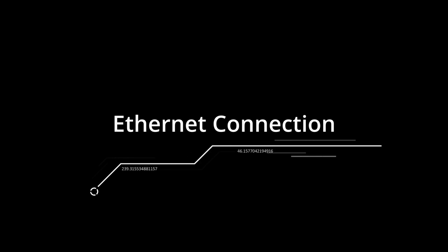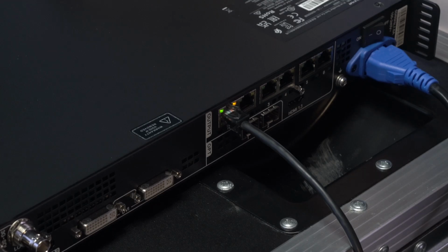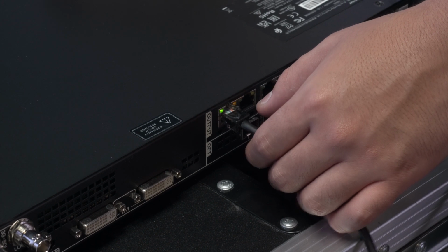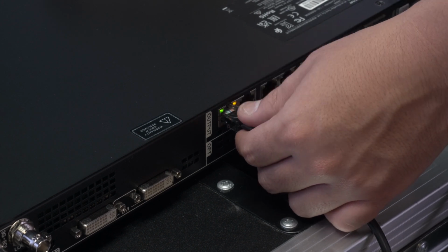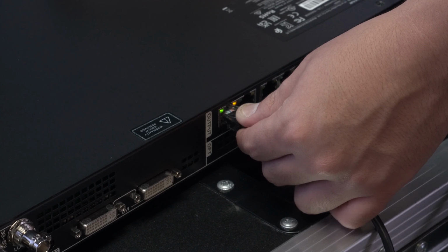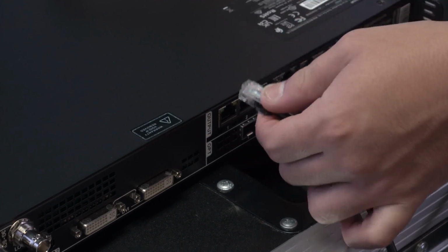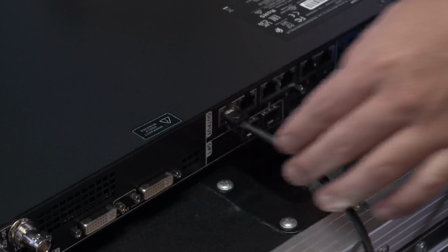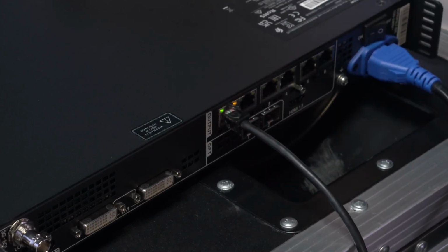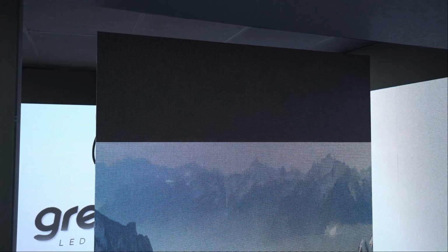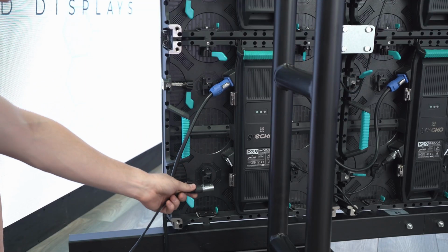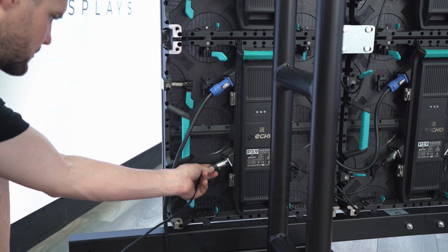The Ethernet cable is not connected or malfunctioning. Make sure you have the Ethernet cables connected from the processor to your LED display, and that the LED display is on. It is always recommended to test with a replacement main cable or UDP tester to corroborate proper operation. If your display turns off an entire section, and you have more than one Ethernet cable, check the main cable by replacing it or testing with a UDP tester.